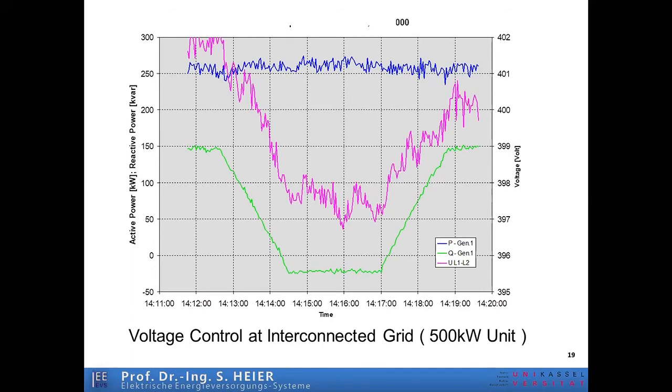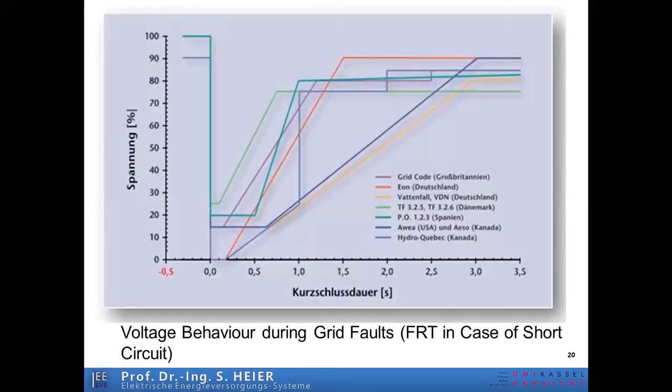This was a European project, and we have done the same in the Canary Islands, Tenerife, and also in La Palma. In these islands, in Tenerife, with about 600 megawatt installed power, we can change the voltage 3%, 5%. In La Palma, we can change the grid 10%. It was not a problem. Yeah, good. This was the result of Dr. Arnold's PhD work also, and we have made a lot of investigation for grid control to hold the voltage about at the same level.